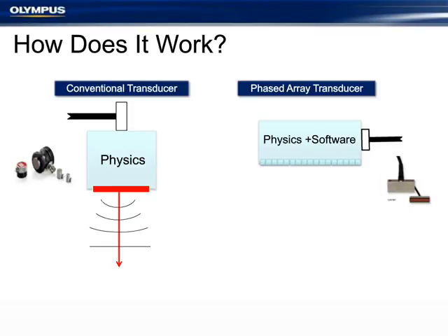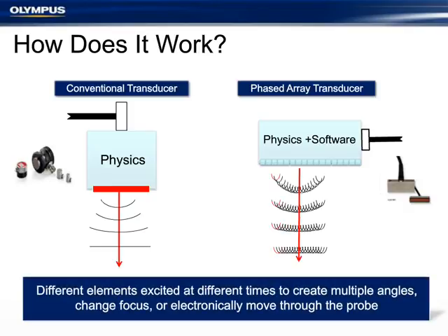So the phased array transducer, we have many different elements all lined up into a single case, individually wired. And we control the different delays to basically form different wavelets that will form together, and using the principle of constructive interference, deconstructive interference, we can actually manipulate that angle.